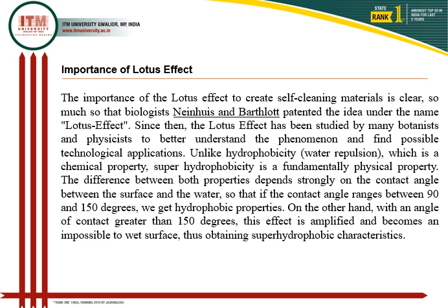The contact angle between the surface and the water droplet plays a very important role for this effect. If the contact angle is between 90 and 150 degrees, then we observe hydrophobic properties. But when the angle of contact exceeds 150 degrees, this effect is amplified and it becomes impossible to wet the surface, and this is called superhydrophobic characteristics.